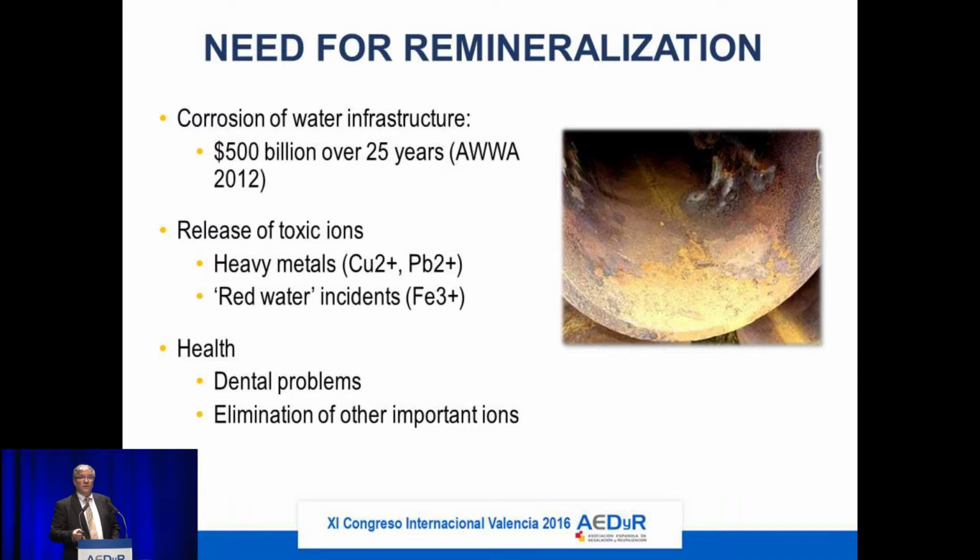So a little bit going back to the need for remineralization. In the United States, they have identified that because of not correctly treating the water distributed in the pipeline, about 500 billion in investments is recognized to be spent in the next 25 years just to rehabilitate or replace infrastructure because of corrosion. Because of this, you have release of toxic ions like heavy metals and these typical red water incidents, which can also lead to health issues like dental problems, and it also reduces important minerals.